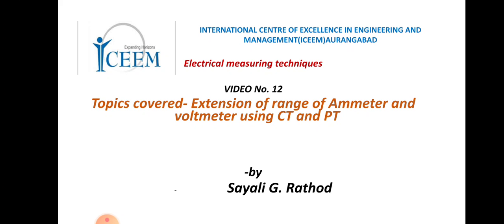But in some measuring instruments there is a need of higher range of outputs where we cannot use the shunt resistance, or we cannot use the resistance in series or parallel for range extension. So for that purpose we need current transformer and potential transformer. In today's lecture we will see why we use CT and PT, and what is the actual process or the circuit which we are using for the extension.